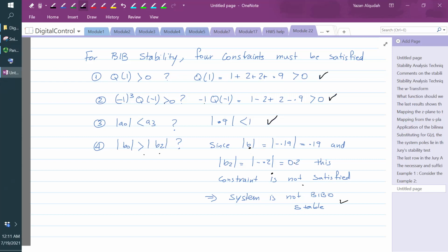Okay, so just to recap what we've done in this module, we looked at the stability of discrete time systems. We are familiar with studying the stability for continuous time systems. We used Routh-Hurwitz to determine the stability of these systems. Routh-Hurwitz applies in a space divided by a j omega axis. It will tell me whether poles are in the left half plane or right half plane.